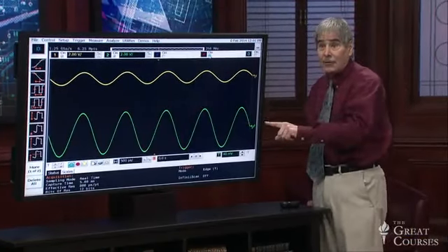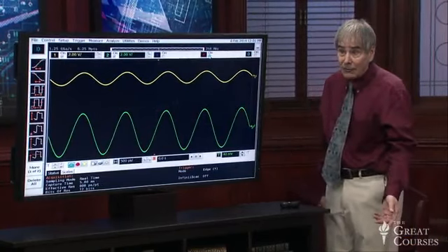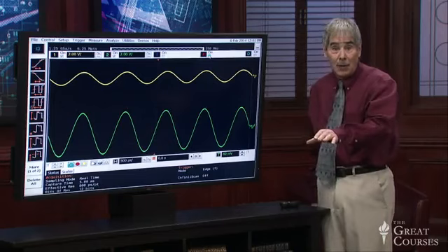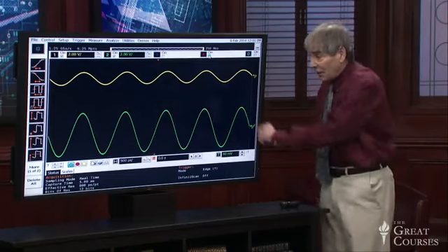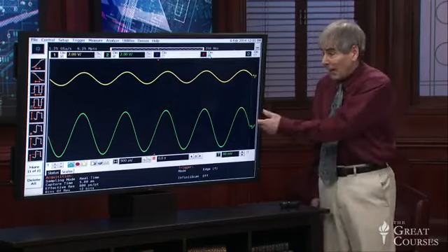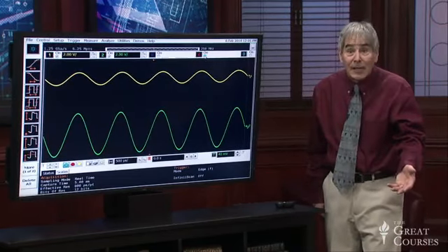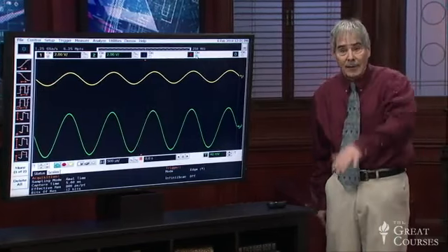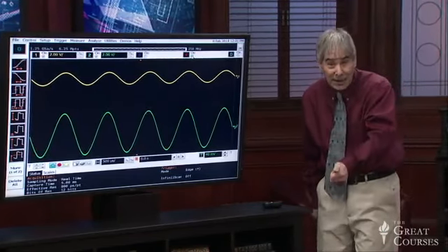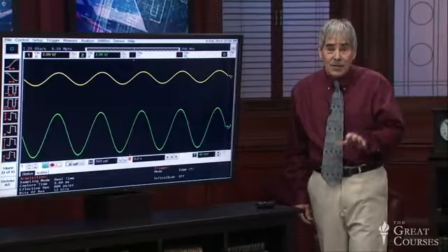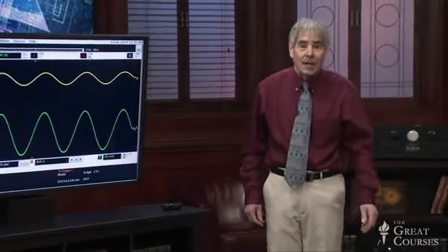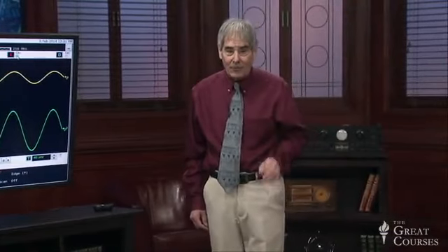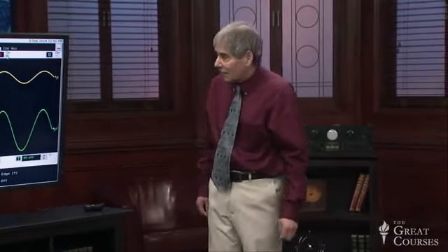There it is. Make it out of 2 inverting amplifiers, one with a gain of -3, the other with a gain of -1. Okay, so that's what we did. Works great. We could have, by the way, had a gain of the square root of 3 in each amplifier if we had wanted, and we still would have come out with 3, but I chose to make a gain of -3 and a gain of -1. So there is a simple embellishment on our idea of inverting amplifiers. Let's move on and look at some other amplifiers we can develop here with these circuits.